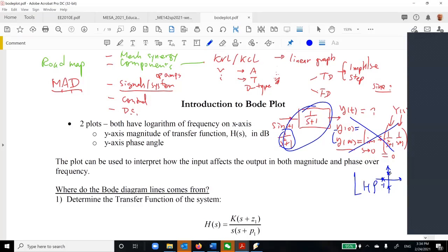So you are not strictly in the LHP, the left half plane, because you have something on the boundary. That's why you cannot do it. It's not applicable. It is applicable only when your poles are in the left half plane. So in this case, you cannot do that.